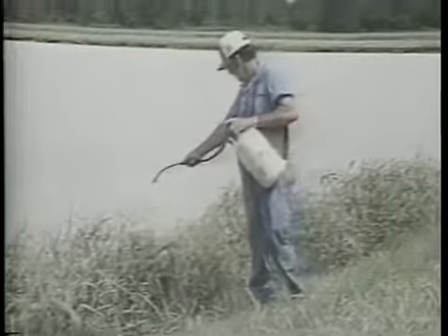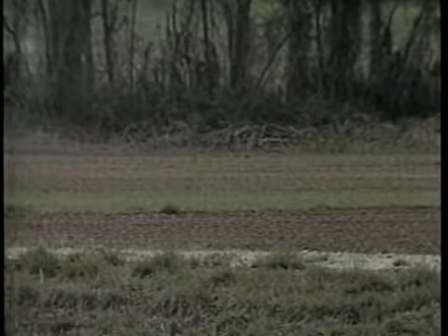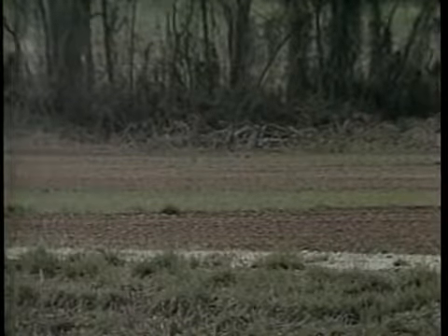Turbidity. Turbid water contains suspended materials which interfere with the passage of light. As mentioned, plankton interferes with light passage, and this is desirable. However, turbidity resulting from clay or other substances is not desirable, as it restricts the growth of plankton. To control turbidity due to clay or organic substances, contact your county extension agent. To alleviate turbidity problems, the watershed may have to be stabilized, livestock and bottom-disturbing fish such as bullheads or mudcats removed, or compounds such as alum may have to be added.